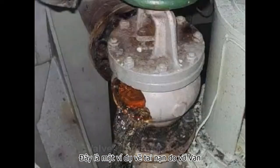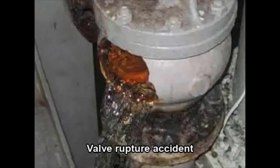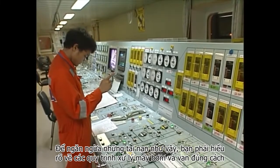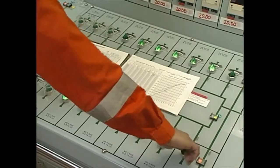This is an example of an accident caused by valve rupture. In this accident, corrosion in the valve body, combined with sudden pressure change due to pump stopping, ruptured the valve body during a stroke to produce a hole in it. To prevent such accidents, you must have a good understanding of the procedures for proper handling of pumps and valves.